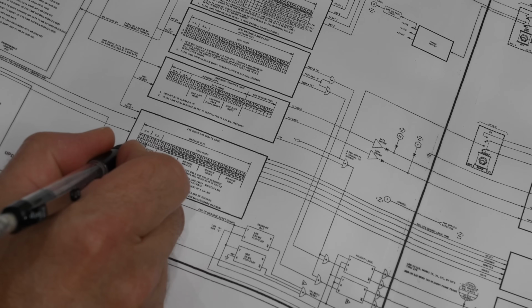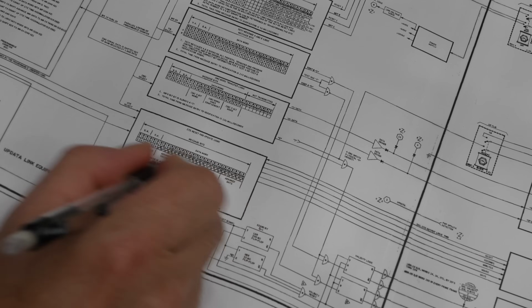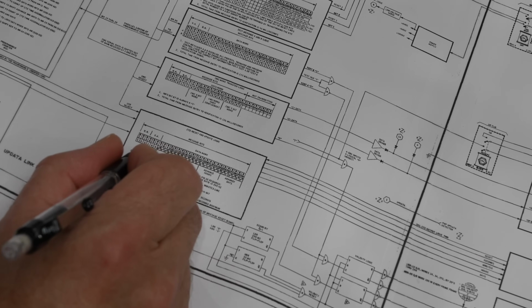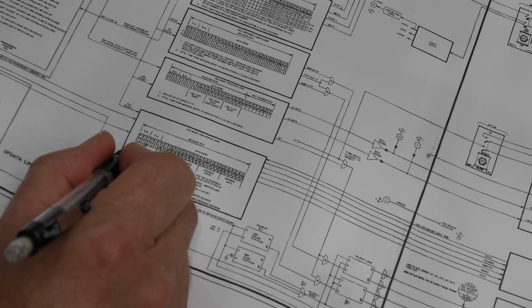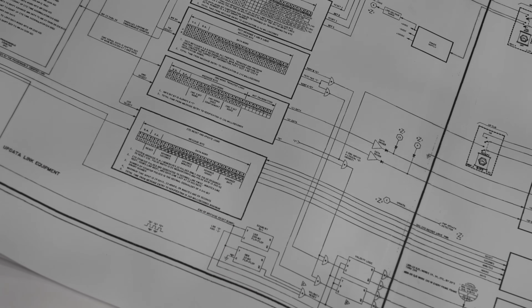And it looks like they switch from big endian to small endian as they move from vehicle address, system address, and then this obviously means 4, so that's the most significant bit over here. But here, the seconds has the most significant bit at the other end. So there's some reversal here that I have to figure out.